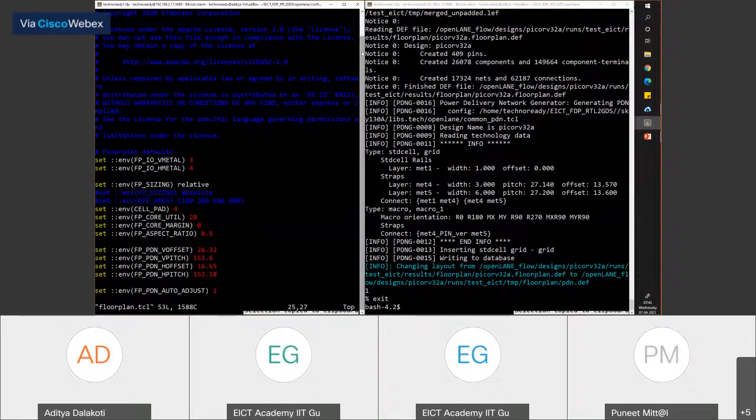Because even if you take 50% utilization, your clock tree might be really complex, and your utilization because of all the clock tree elements might go up further. We'll come to all those concepts later. And if you pick a really big area, then your clock distribution network might consume a crazy amount of power. So yeah, it depends on what is needed at that point of time. You have to define a spec to measure the performance, basically.